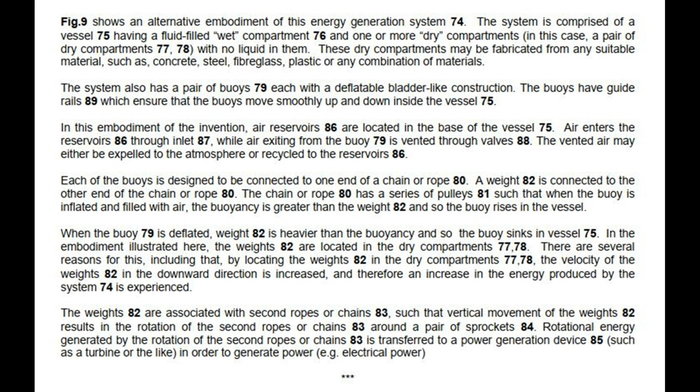The system also has a pair of buoys 79 each with a deflatable bladder-like construction. The buoys have guide rails 89 which ensure that the buoys move smoothly up and down inside the vessel 75. In this embodiment of the invention, air reservoirs 86 are located in the base of the vessel 75. Air enters the reservoirs 86 through inlet 87, while air exiting from the buoy 79 is vented through valves 88.